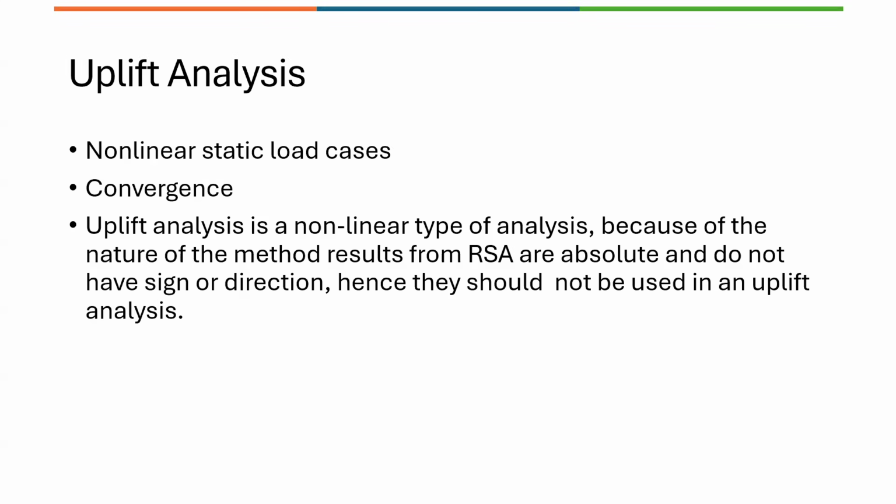However, for the foundation, specifically for this foundation system, you can always convert this response spectrum as a user load in the ETABS model itself as a linear static, and then use that result in your foundation design. That is the simplest way of doing it, and it's our recommendation specifically for the foundation systems, right?